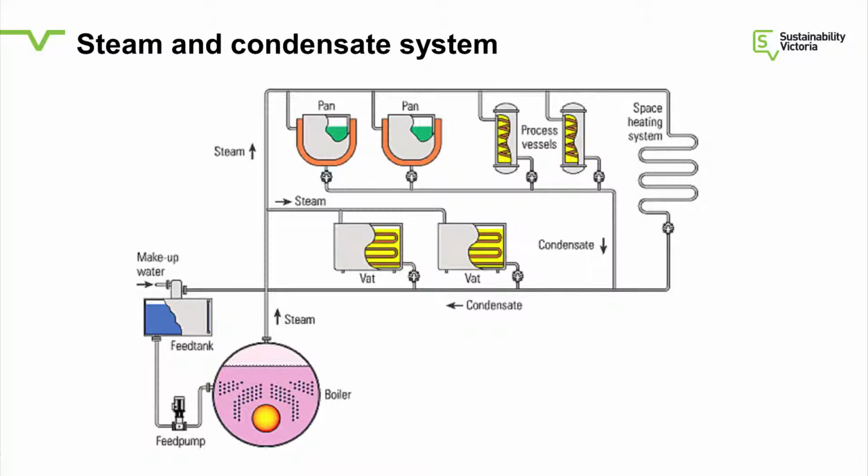And as I said to you before, a steam trap stops live steam going, but it allows condensate, the condensed steam, to go. So what happens when the energy is absorbed out of the steam, it condenses, and you've got to extract that condensate out so that the unit continues to heat. So in all applications, you'll have some sort of steam trap.